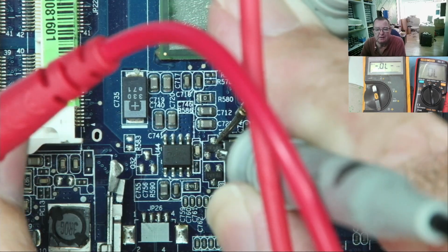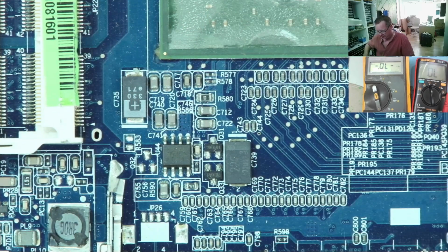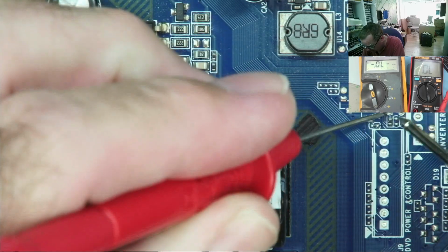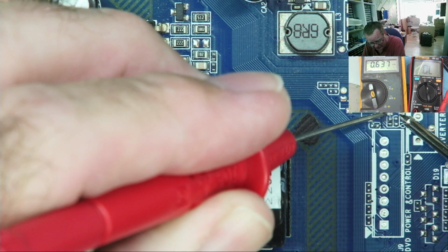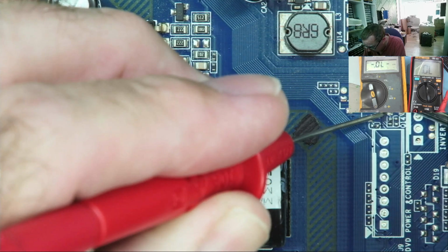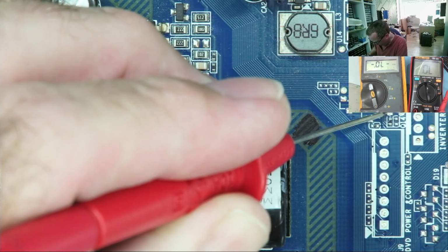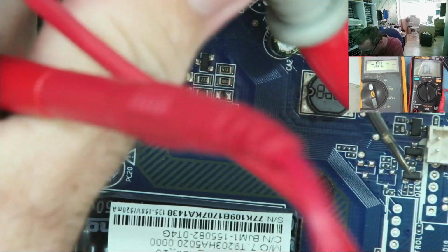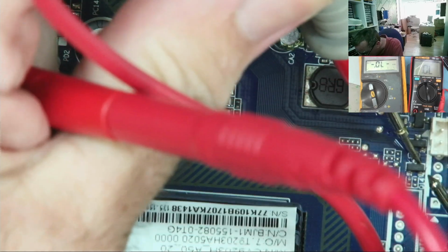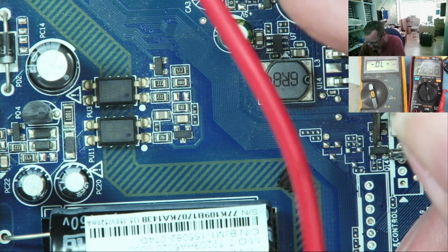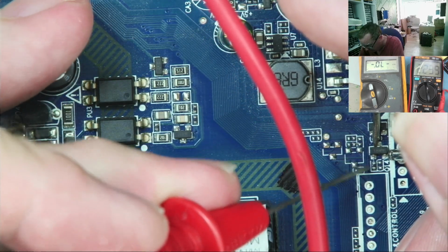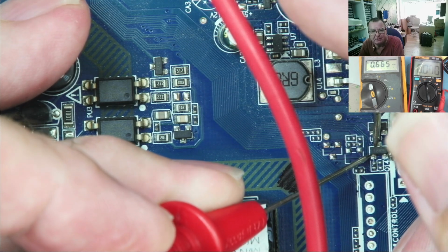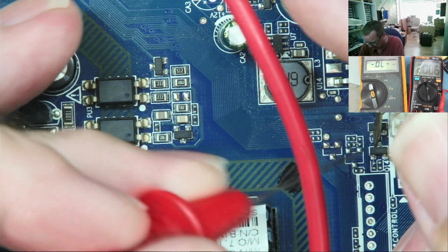I can test it. And I can do the same thing with bipolar transistors as well. This is a bipolar transistor. I can go onto the base, onto the emitter. I have a diode junction on the Fluke. Collector, have a diode junction on the Fluke. Let's connect the Aneng collector emitter with the positive to the collector. Okay, again, we really want three hands, but we'll manage. So I'm now connected across the transistor. Now I'll come onto the base with this one. Look, you see a diode junction now, base emitter, and you can see that the transistor is switched on if you look at the Aneng. Okay.